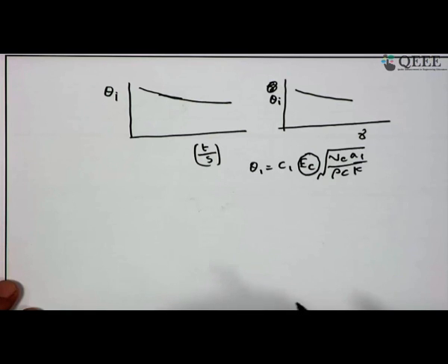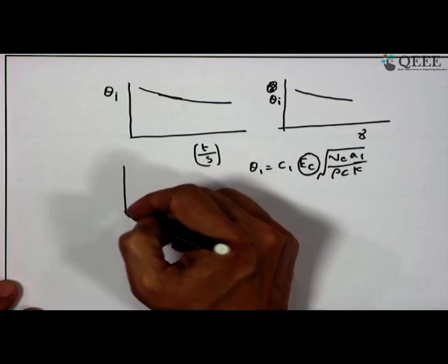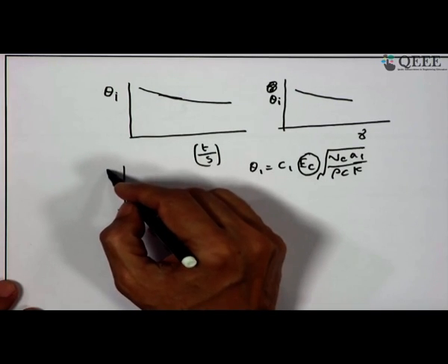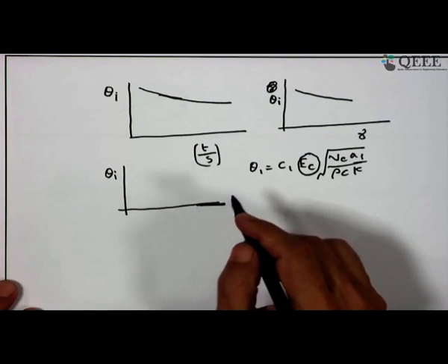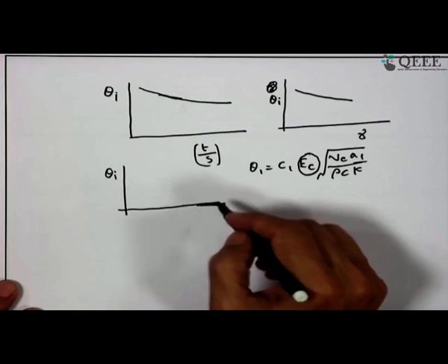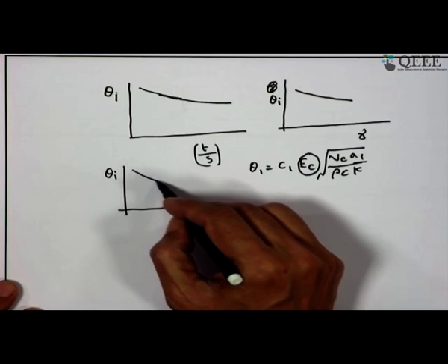Otherwise, if we give a positive rake within reasonable limit, within 5, 10, 15 degrees, we get immediately a positive effect. Similarly for alpha, if we look at theta I and alpha, we see that if we avoid rubbing, then at some point we can have a reduction of this temperature.